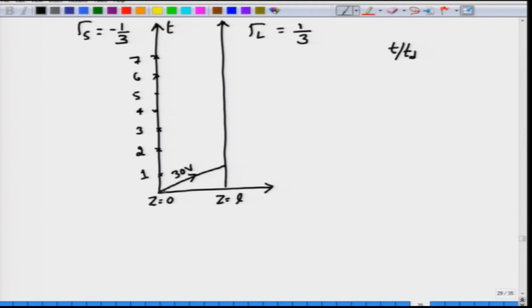So, that is the reason why we have written this as a line here. If there was some kind of a nonlinear length to delay relationship, then this could have been a different curve, but luckily as you start increasing the distance, the propagation time will be L by u, u is constant and L is the one that is linearly changing, and therefore delay changes linearly.